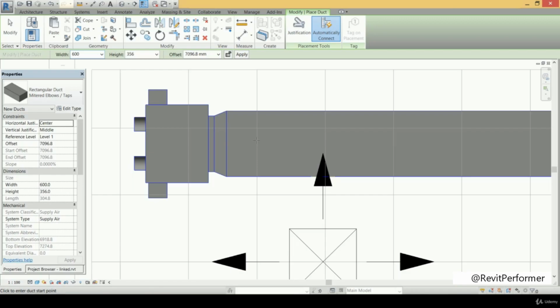But in the practical design, the main duct is larger than the VAV box neck, so we don't connect the neck directly on the VAV box. We go out of the VAV box with a duct that has the same dimensions as the VAV box neck, with a specific length, and then we connect that duct with the main duct that will feed the diffusers or that will go out of the VAV box.